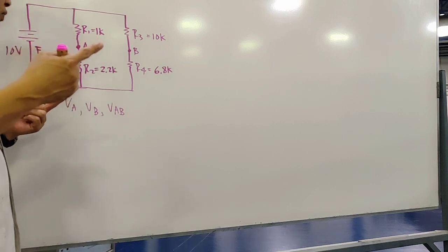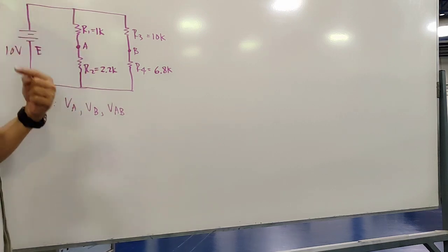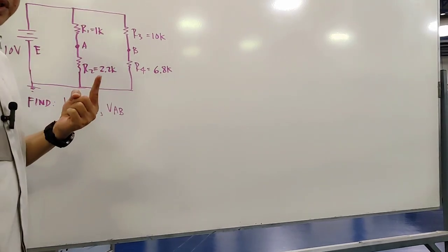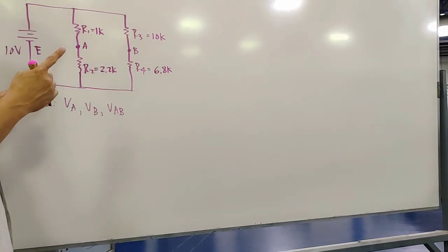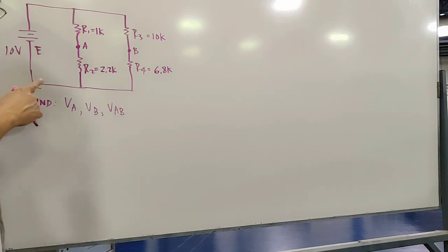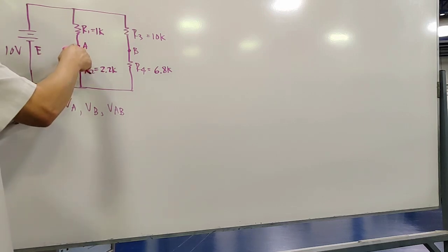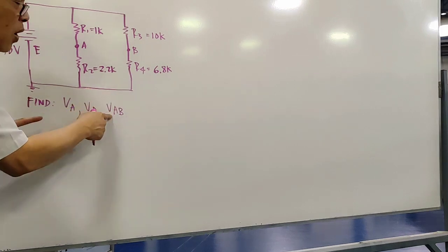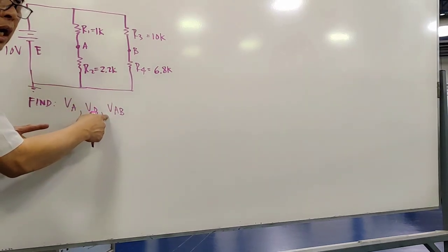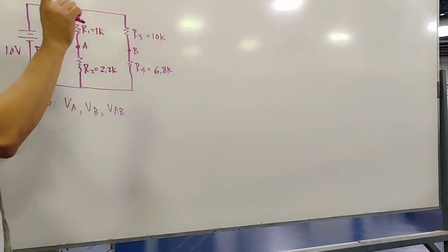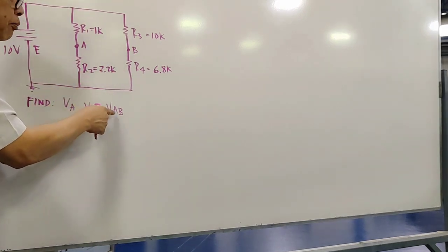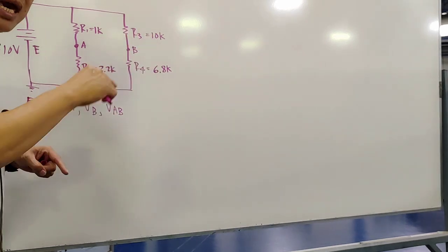As I mentioned before, how to measure. So imagine yourself as the DMM, the multimeter. You have the negative, you have the positive here, correct? So to measure VA, one from ground, one from VA. So that's the VA voltage. VB voltage. So now, how about VAB? One not on the ground, one put in A, one in B. Yeah, that's the voltage between points A and B.